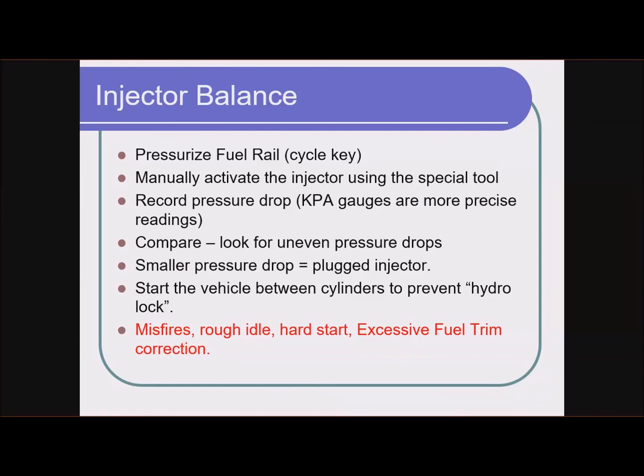You manually activate the injector. We have a special tool that will connect directly to a fuel injector, right to the electrical connector. With the push of a button, it'll fire that injector for, I believe, 100 milliseconds.